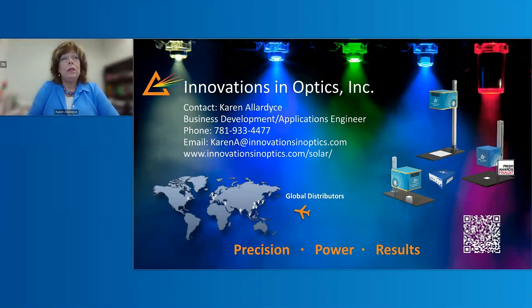It's not easy to do. We take great care in our optical design and layouts of the die and choosing the proper wavelength distribution. For example, why it matters, for example, to tandem devices. Each subcell responds to different spectral regions. So if those wavelength regions are non-uniform, then the subcells experience different biases across the field. In essence, it will cause incorrect current matching, shifts in fill factor, for example, and inaccurate efficiency values.